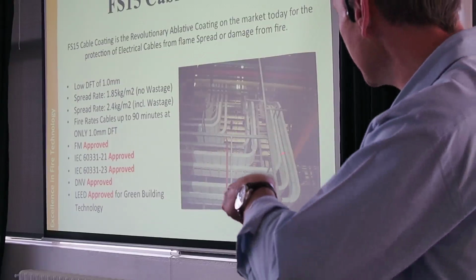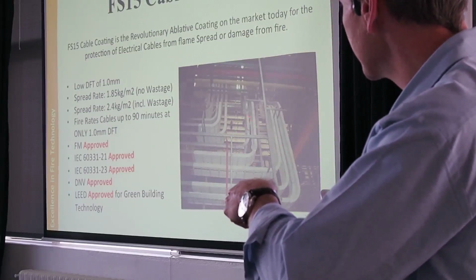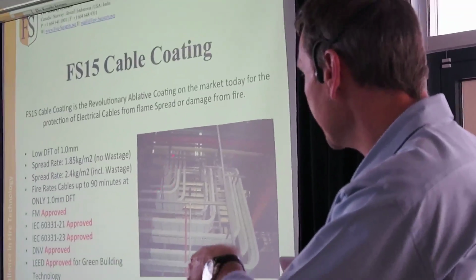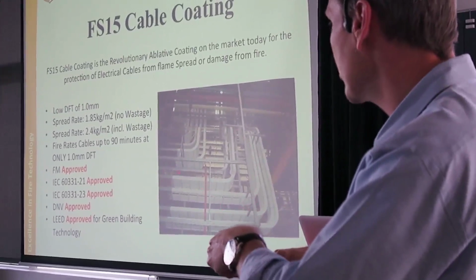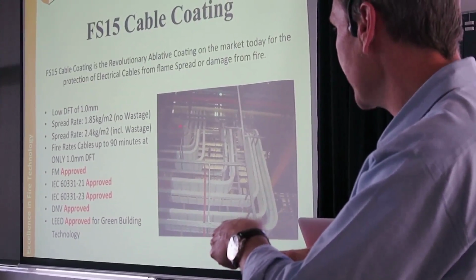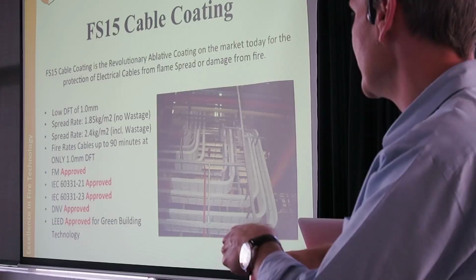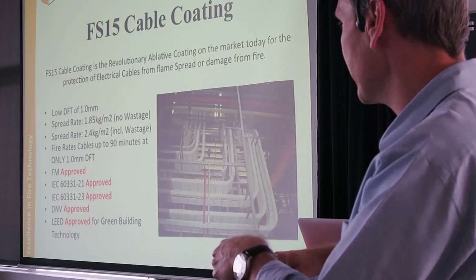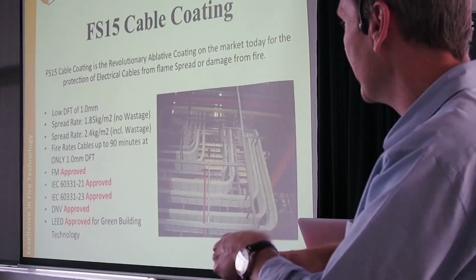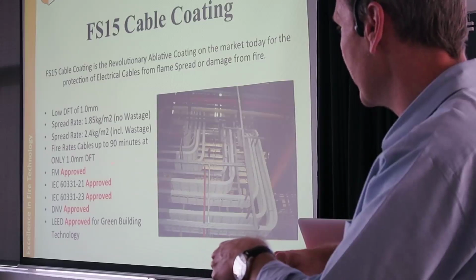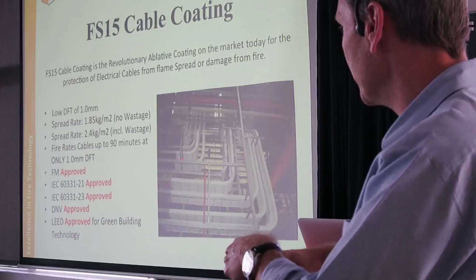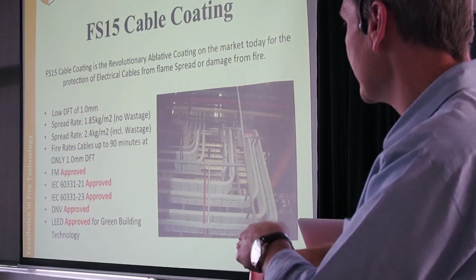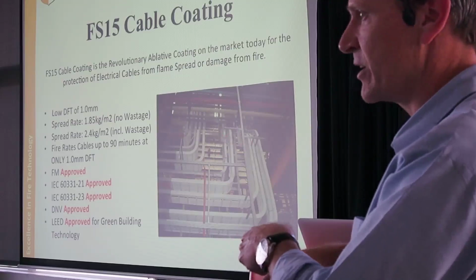For instance, in this picture here, you'll see a guy in the background up in a steel plant. What they're doing is cable coating these massive amounts of trays, but they're not doing all of the trays. This is actually open air. It's called open air stitching or fire stopping. We do this because they're willing to lose an amount of cable, but still willing to stop the fire. So the cable trays, which are running all the way along, that fire will stop at this point. It will not spread up here and then go to the interchange areas over here where other trays are running into the sections and then running to other sides of the plant.